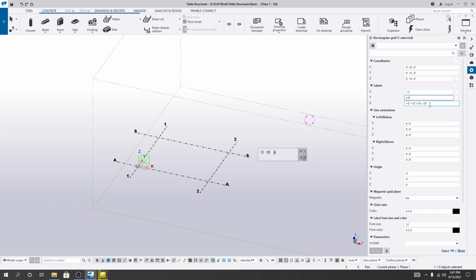And also for the z direction, here the 0 level, then our level 10. Also if you need to change that value for the base level or any other value, you can also add it here. Clear? So here 0, then I'll take another level, plus you must provide a spacing between them.